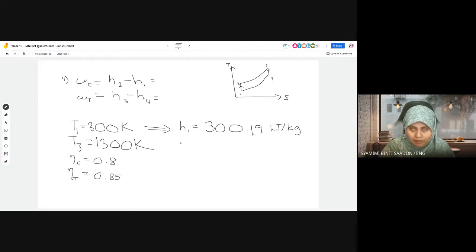From the same level, in the same table at temperature 300 Kelvin, the pressure ratio is also stated in the thermodynamic table. If you look at table A17, you can take that pressure ratio PR1 from the same level: 1.386.